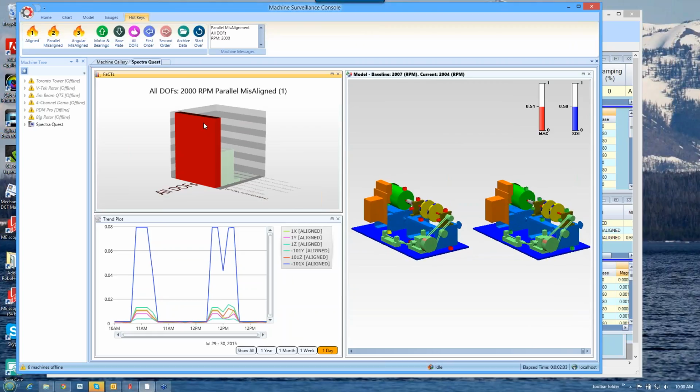Any other question? Machinery people typically like to look at velocity. It's kind of the happy medium between acceleration and displacement. But if we truly wanted to look at displacement, now when you look at the animated picture, you're looking at an amplified version of acceleration. So would the displacement look like this? Yes, it would. It would look very similar when we're simply displaying ODS data, because the animation will scale it so that we can look at it.